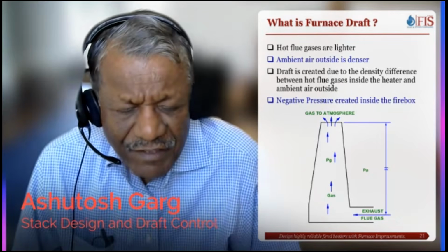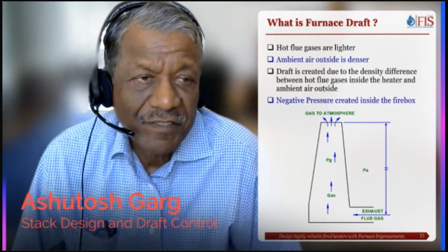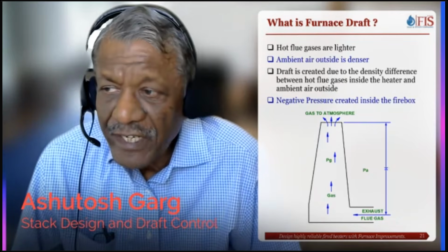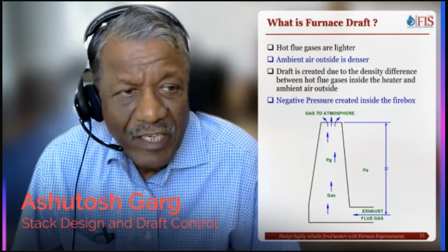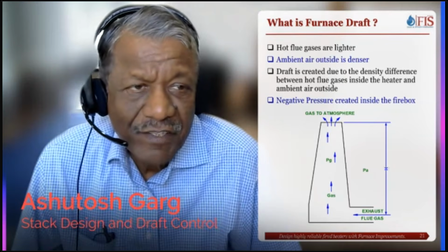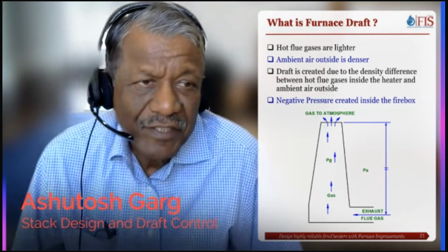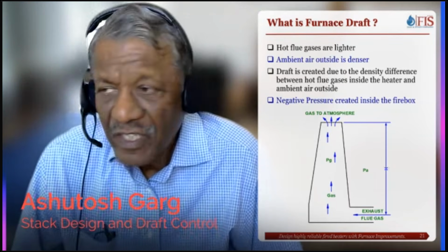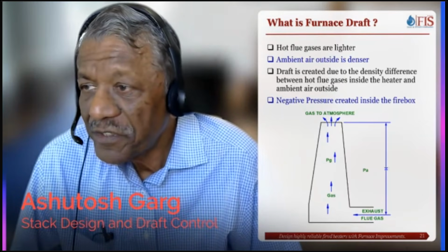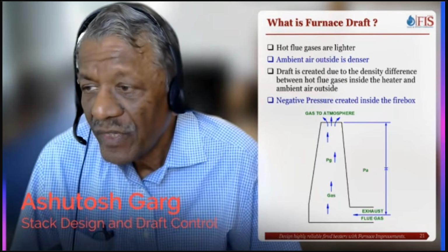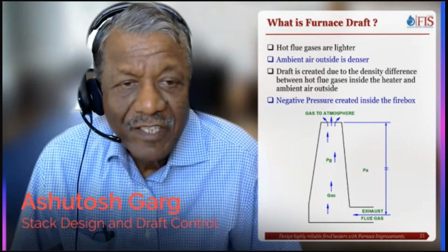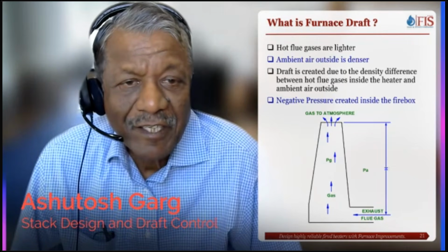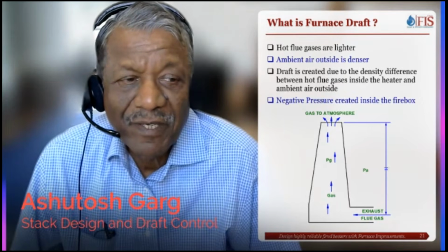Inside the furnace we have hot flue gases, and outside the furnace we have cold ambient air. Because of the density difference between the flue gases and ambient air, a driving force is created, and that driving force is used for supplying combustion air to the burners.